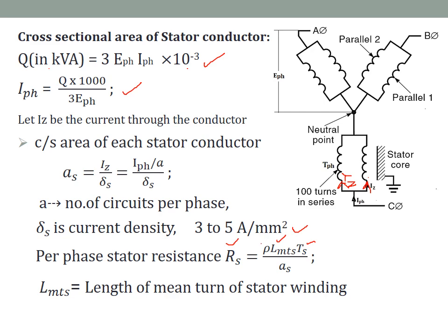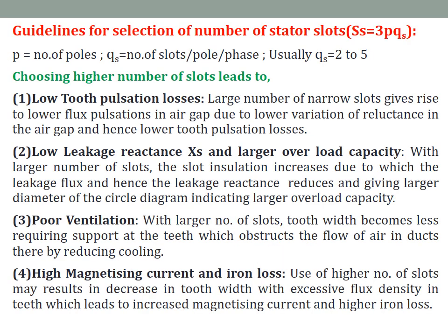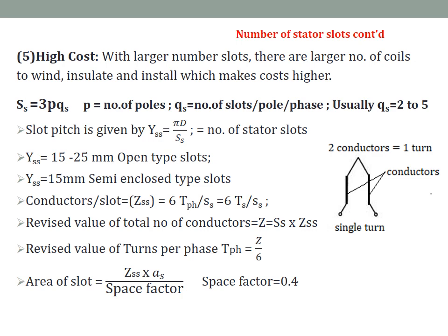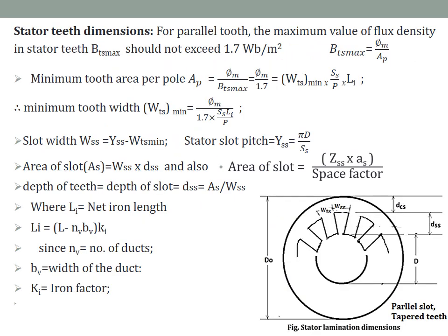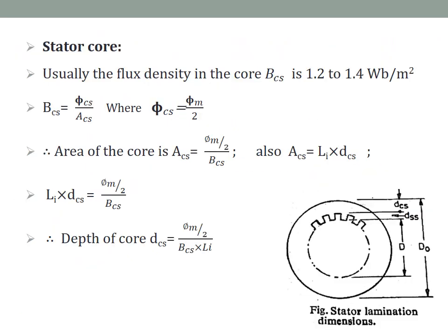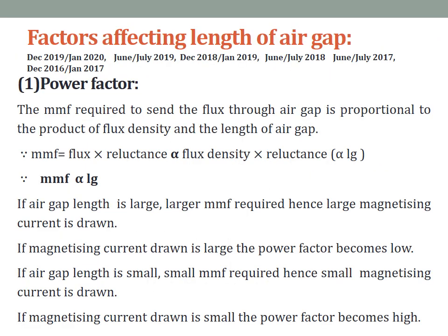You will understand how to calculate all those dimensions by analyzing the equation. Now, after finding the stator details, we move on to the air gap length. You can see that there is an air gap between stator and rotor. The air gap you may design with minimum length.